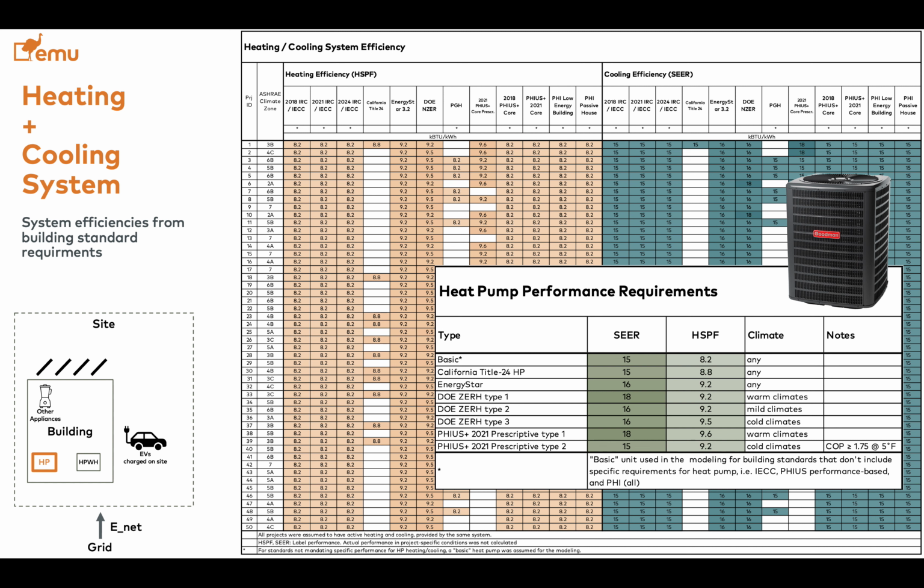We talked in one of the earliest videos about the priorities between heating and cooling. And this is one of the reasons why we typically recommend prioritizing heating efficiency even in hot climates, because heat pumps are better at producing cooling than they are at producing heating.